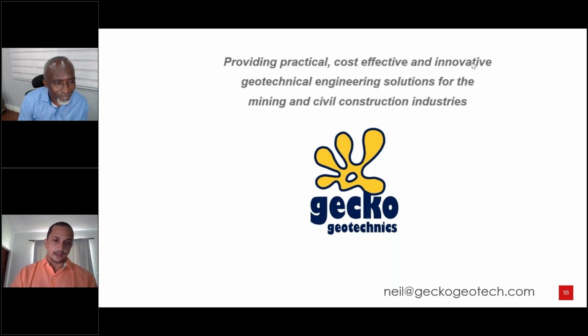Okay, let's tackle one at a time. So riverine erosion causing landslide: InSAR should definitely be able to detect the deformation. You may have to use a different type of InSAR if there's a lot of vegetation, and that's advice you can get from the service providers. In relation to underground workings collapse, of course, InSAR can also do that.